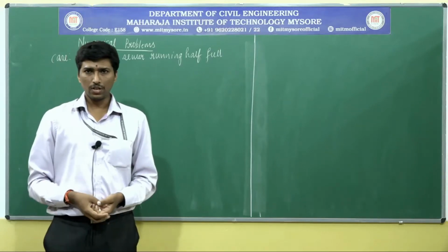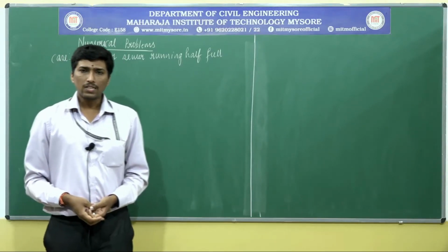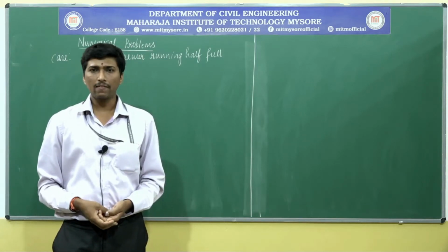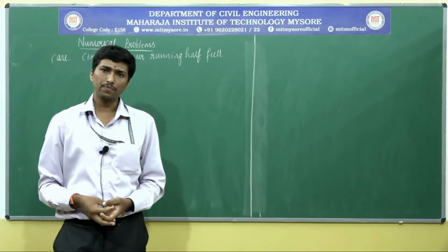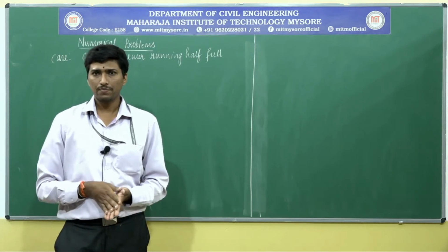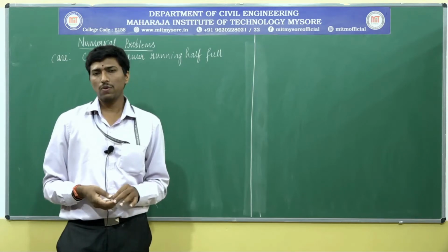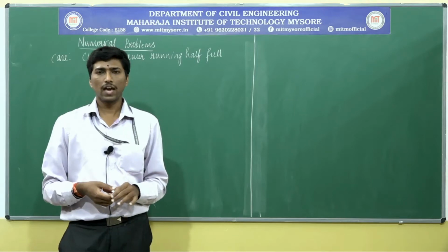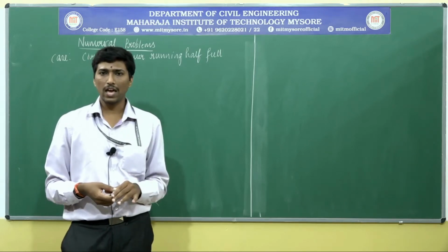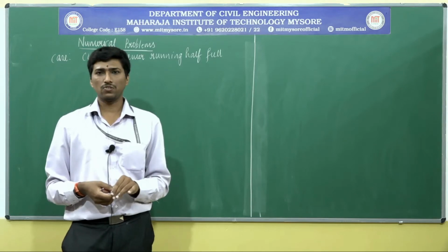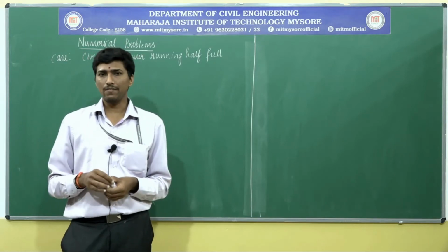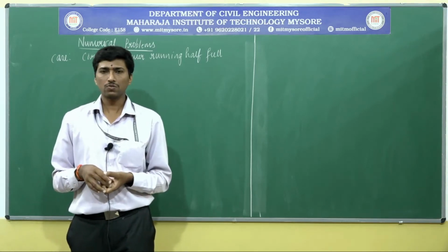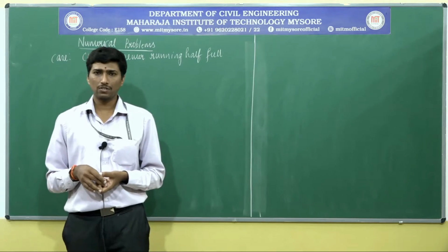Welcome back to session 3 of module 2. In the previous class, you came across numerical problems, mainly dealing with the usage of hydraulic formulas, Manning's coefficient. We also came across Kutter's equations and the Hazen-Williams equations. Normally in India, we design the sewerage system using Manning's formula, which is suitable for our tropical country.